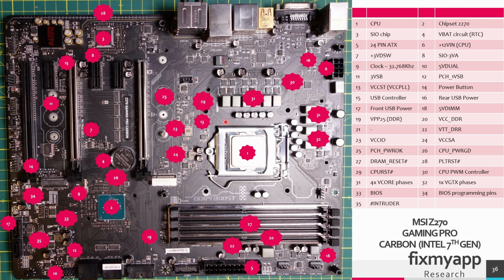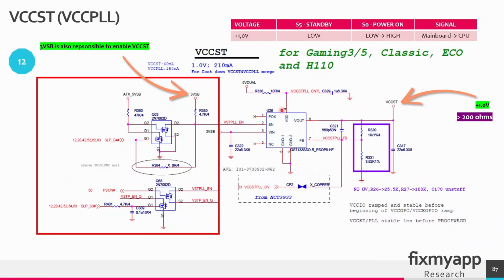This is CPU, and near the CPU there is a voltage regulator that will create the VCCST voltage rail that will go to the CPU. Also, the power good signal will go to the CPU. This is the voltage regulator that will create the 1V for the CPU. The power supply for this voltage regulator comes from the 5V dual voltage rail, and that derives from the 5V standby voltage from the ATX power supply or the 5 VCC pin from the power supply when it's turned on.